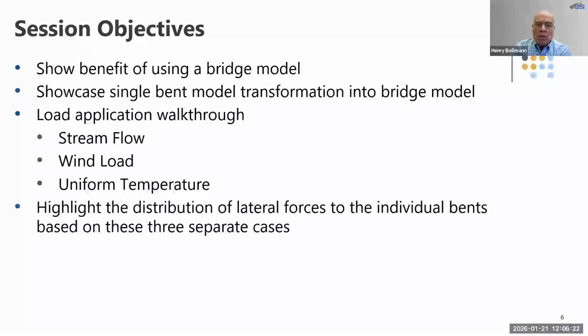For generations, people use simple pier models, and they work very, very well, especially for long bridges, constant water depth, constant pier, substructure stiffnesses. And when we have that situation, then using tributary areas for computing load cases works very, very nicely. But if you don't have that situation, then a bridge model can be very, very beneficial.